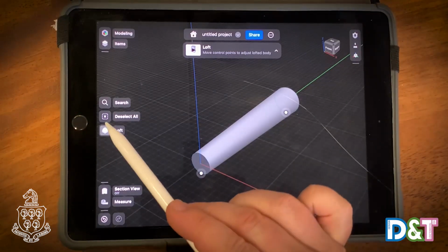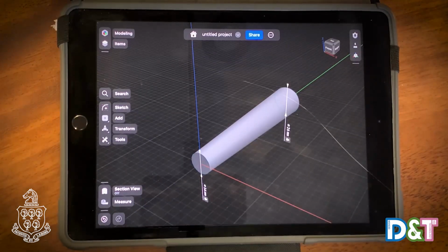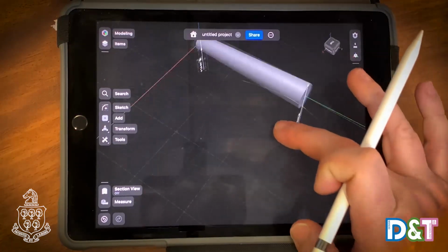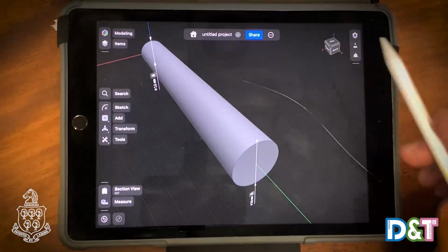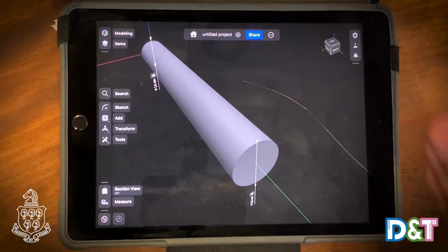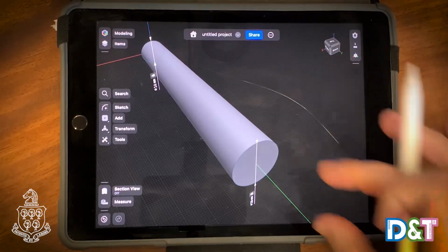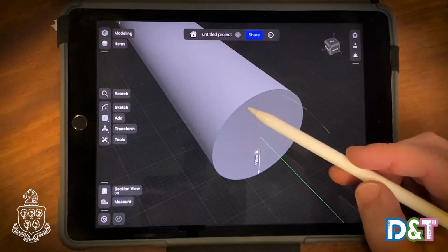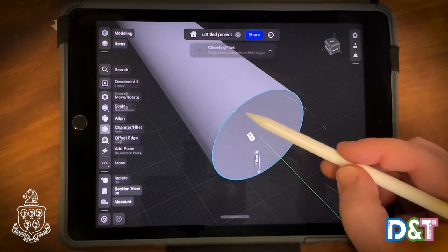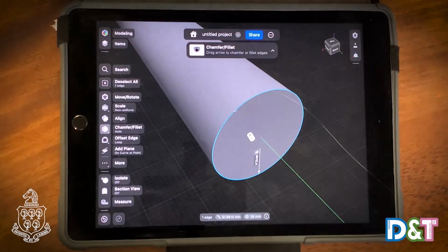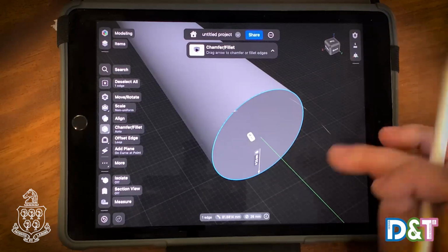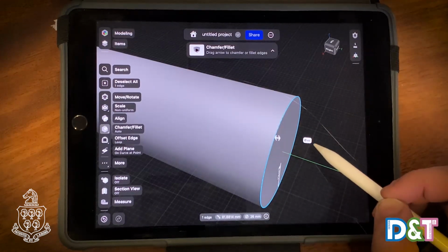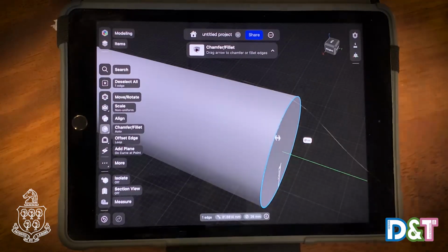And all I'm going to do now is hit the Deselect All button. When you look at the engineering drawing, you can actually see the end of the handle isn't actually a flat end. It is actually a really nice domed radiused end to it. So I'm going to show you how to put a really nice radius on this end. So with the pencil, really carefully, you're just going to click on the outside edge of that end, and there you should see two things. You'll see a double-ended arrow, which you can manually pull out and move, or that dialog box where you can actually type in what you want.